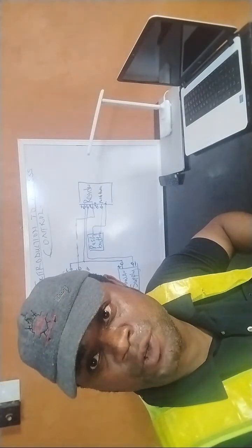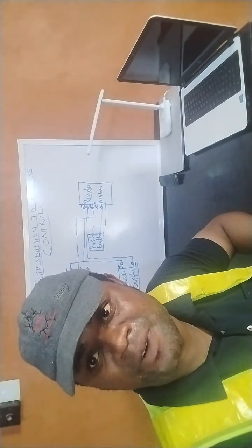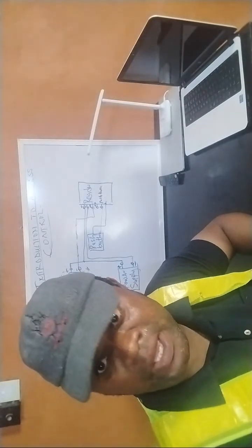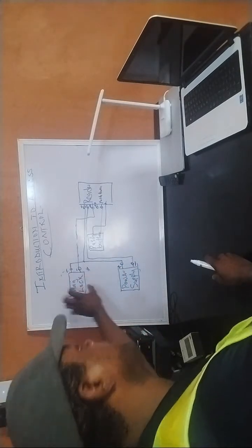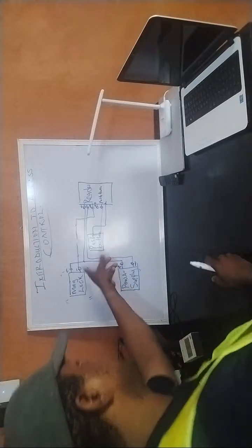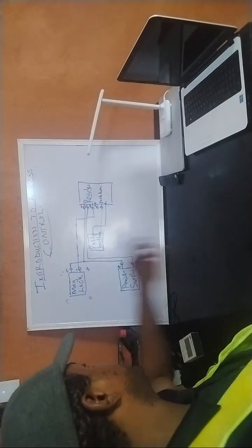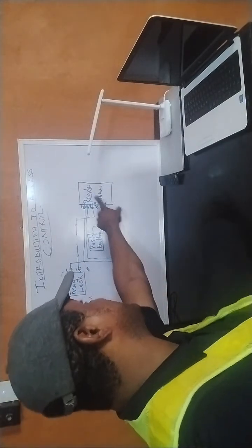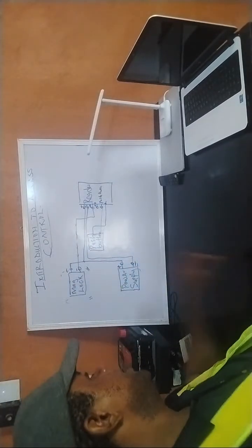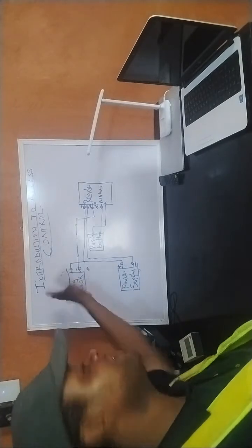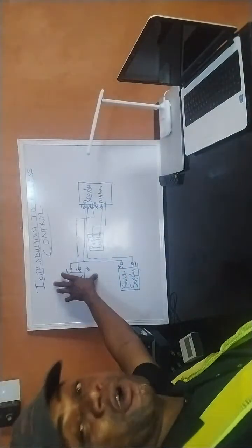He said the normally closed from the reader is connected to the negative of the magnetic lock to power it, right? Yes, because the positive here has already gotten here. All this guy needs here is the ground or the negative to hit this other part for it to become active. So it is from this reader that the negative signal is supplied for this to be active. Immediately this one gets here, this one energizes. When it energizes, it brings the other part of the door together and it's locked. This only works for the magnetic lock.